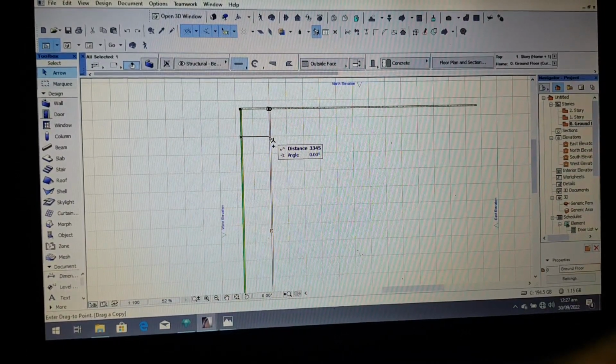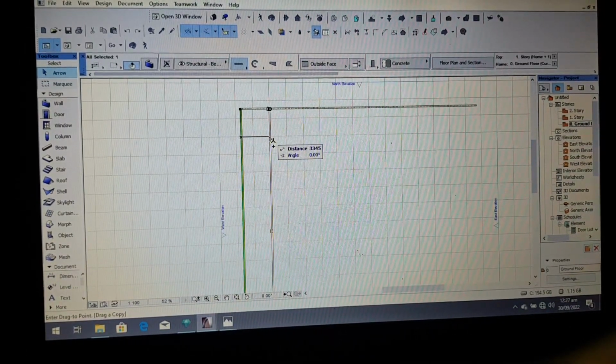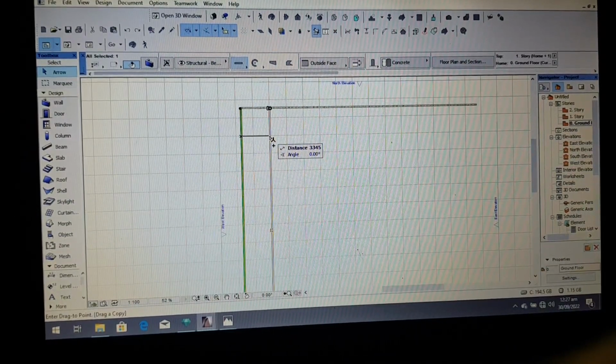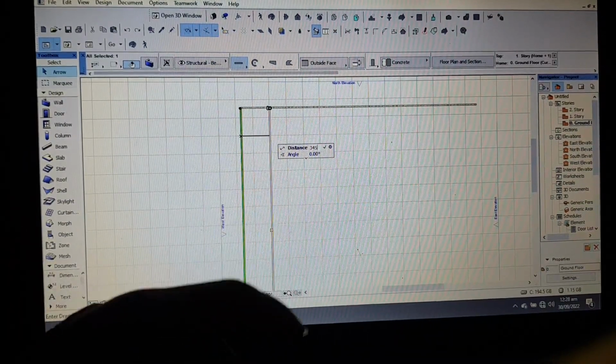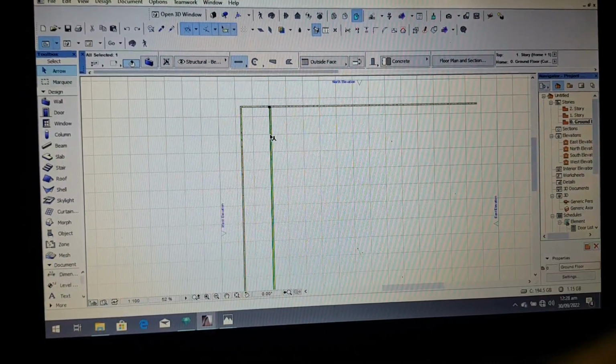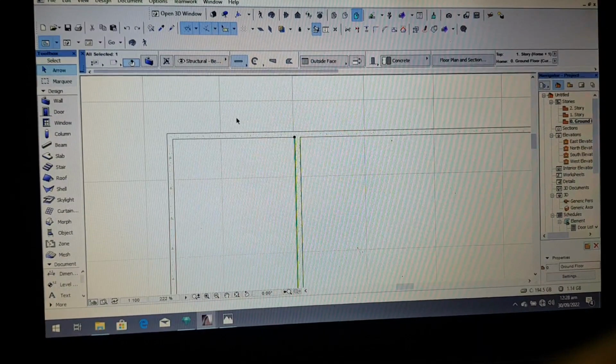So now let's give this room 3.3 meter. Then you add your block thickness. That's 150 mm plus 3.3 meter. That's 3450 mm. You can see it very well. You click this. There's a room.